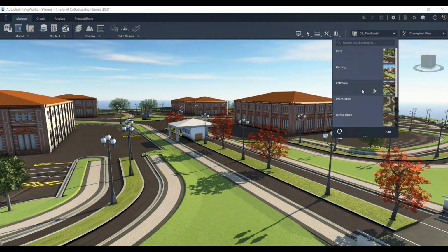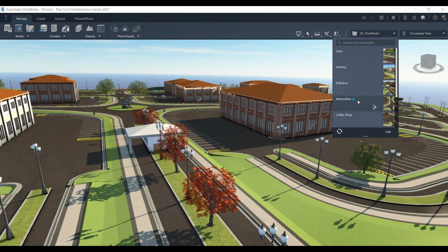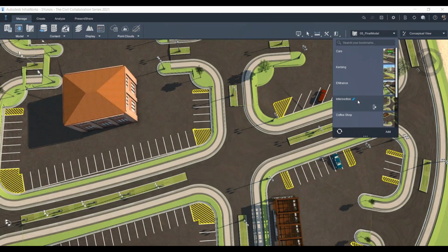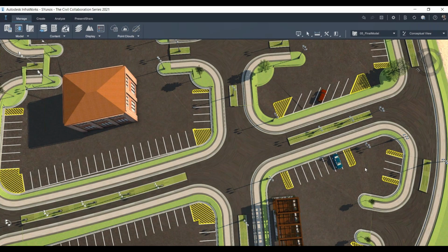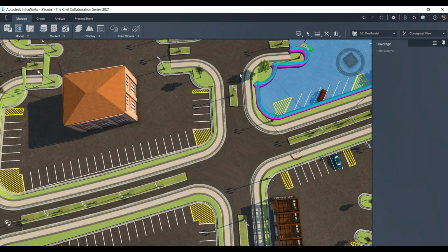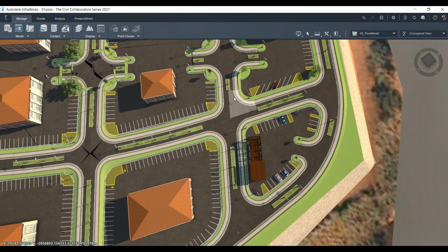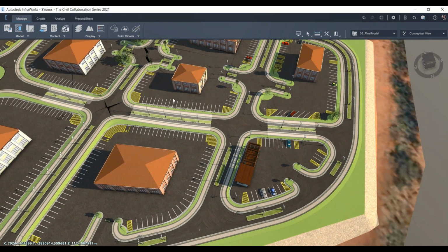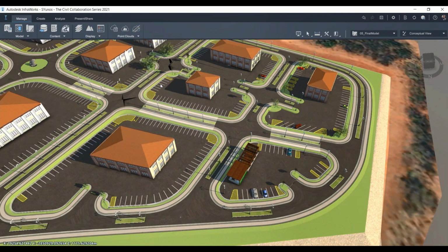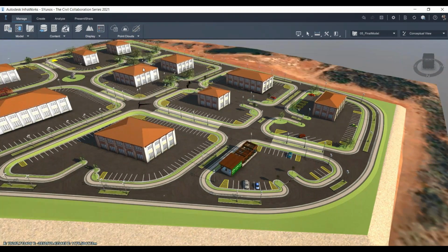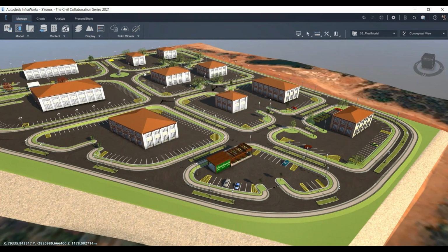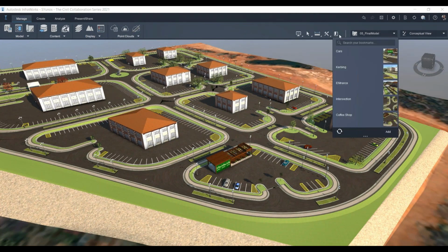We've got light posts, shadow effects, render materials, and look how cool the intersection looks. This is from Detailed Design, and it looks really well. If I click there, you can see it is actually from Civil 3D, the parking areas and so on. All of the corridors came in pretty good, right? But the key to this is you need to not rush it in Civil 3D. If you do, you're going to run into a lot of back and forth between Infraworks and Civil 3D. So get your civil design right in Civil 3D, and then Infraworks becomes quite easy.